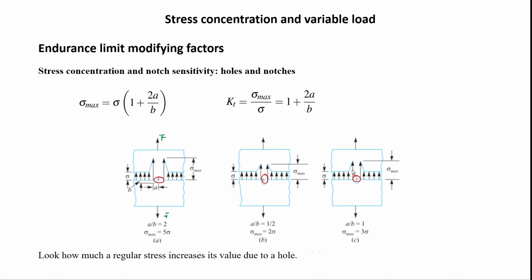How much is that increased stress? Meaning these ones here. So this one, and this one. Well, the maximum stress is going to be this one. Imagine having an elliptical hole oriented with the largest axis perpendicular to the direction of application of the force; it increases locally the stress by 5.